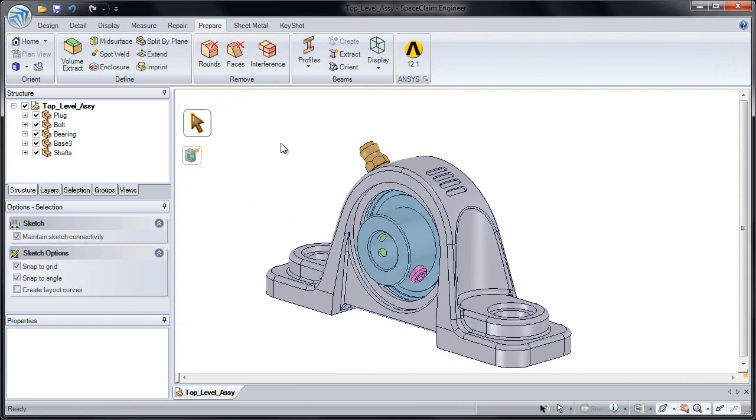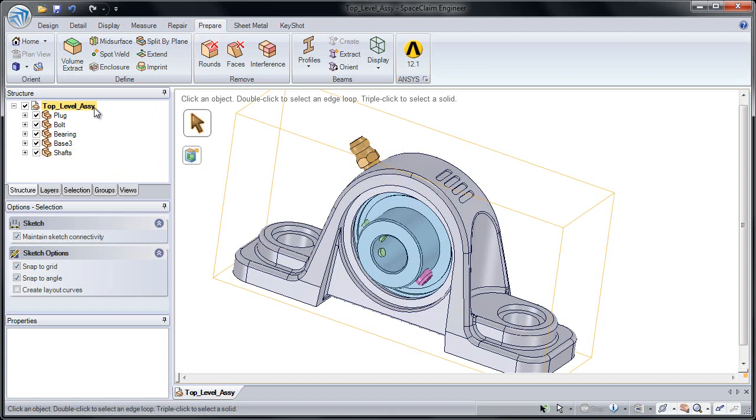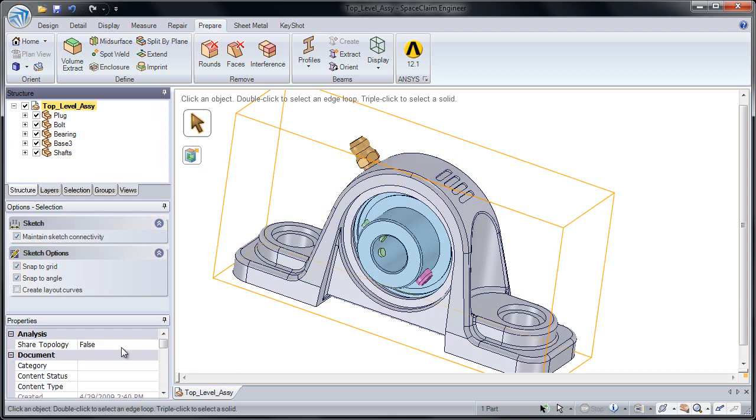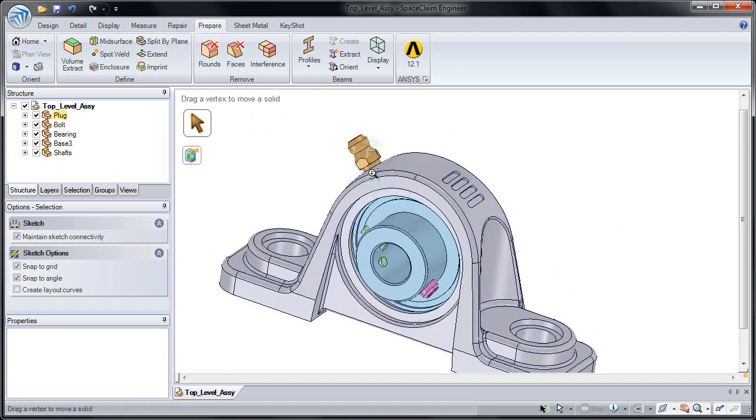Now let's move on to Imprint. Because let's say we want to set up a good mesh between our bodies. So we want to have the faces the same size on each part. Now, if we're using ANSYS, you can always use shared topology and just set that here. But we will go into more detail with that in the ANSYS class. For anyone else who's using other programs, it'll be important to know how we can use Imprint.